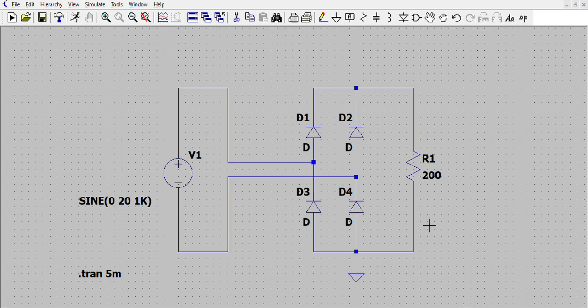What I can say about this is, I want to explain the impedance characteristic of a large inductor in DC and AC. For large inductors, impedance in DC is considered similarly to resistance, which is defined as voltage across an element divided by current.